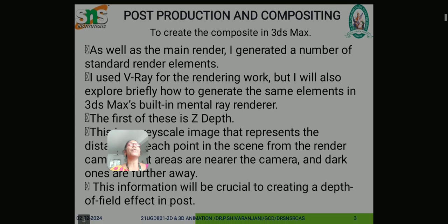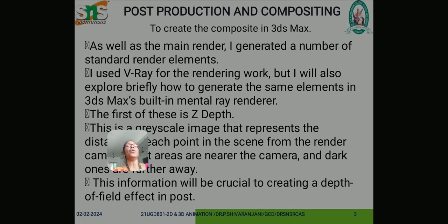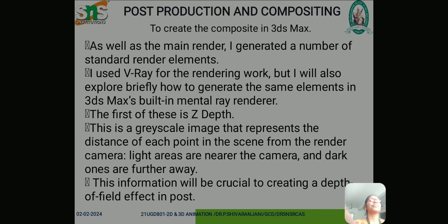To create composites in 3D Max Studio, as well as a main render, you first generate a number of standard render elements. I used V-Ray for rendering work, but I will also explore briefly how to generate the same elements in 3D Max's built-in mental ray renderer. The first of these is depth.